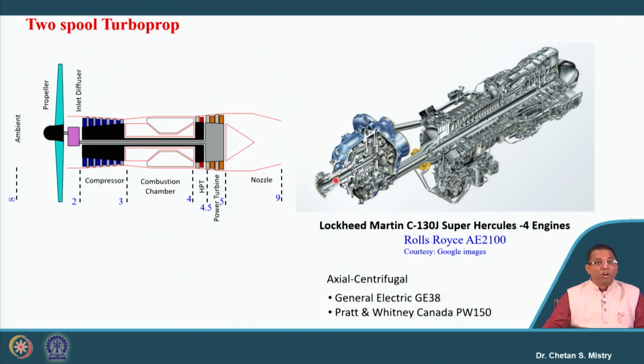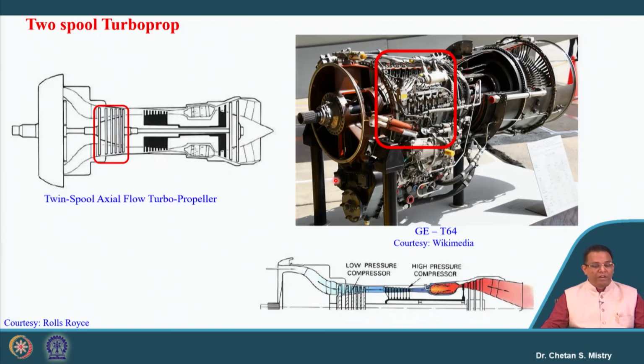We have discussed earlier that there is a special requirement of compactness for these engines, and in order to reduce the number of stages of the axial flow compressor, we go with a centrifugal compressor. But the challenge with the centrifugal compressor, as we discussed earlier, is to turn the flow from axial to radial direction, and again we need to configure our flow in the axial direction because we will have turbines of axial configuration. So as we go ahead we will get an understanding of that part.